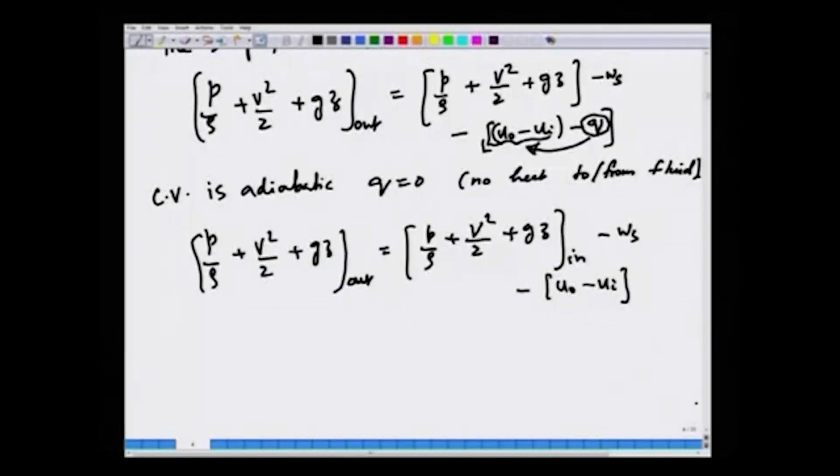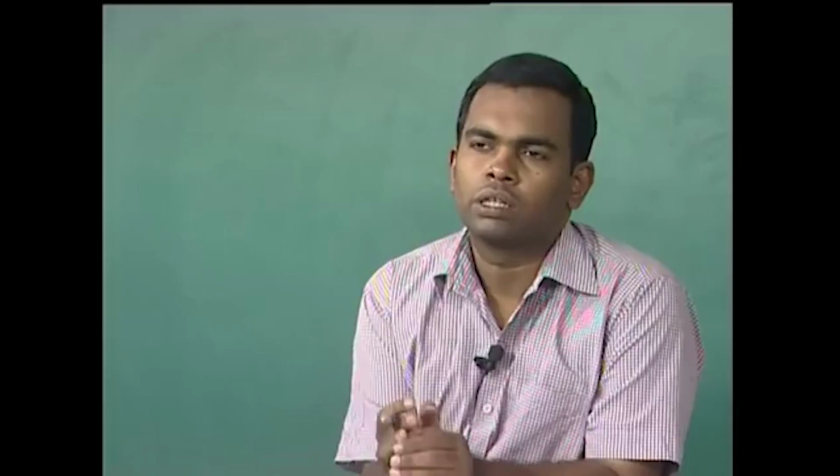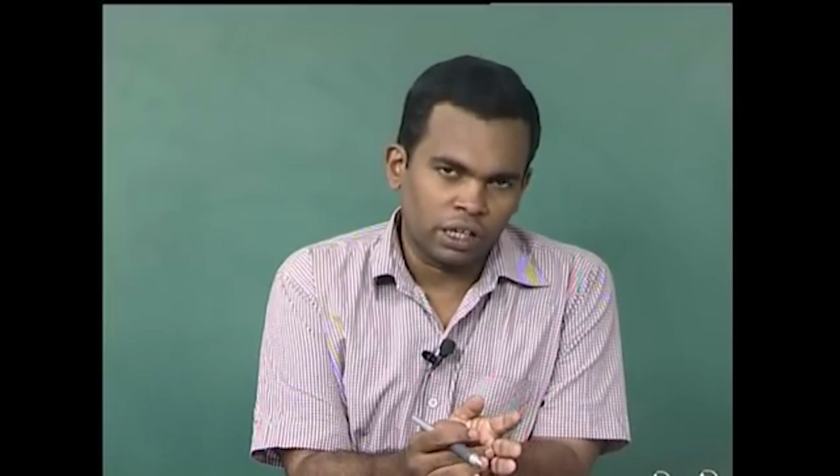Now, there is no heat transfer. The question that we can ask is, will this term be 0 or non-zero if there is no heat transfer whenever there is a fluid flow? It turns out that whenever there is a fluid flow happening within pipes or in equipment like pumps or compressors, there is always an irreversible conversion of macroscopic mechanical energy to internal energy.